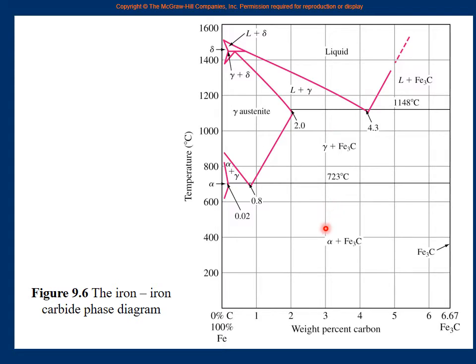So now, if you remember your eutectic point. What was the eutectic point? Can you remind me? Think back from the previous lectures. Normally, when you have liquid metal and it is binary like iron and carbon here or lead and tin, and you slowly cool it, then liquid first becomes liquid plus solid and then it becomes solid. What happens at eutectic? All the liquid turns into solid, right? And usually it turns into two solids. So is there any point like that here? All the liquid changes into two solids.